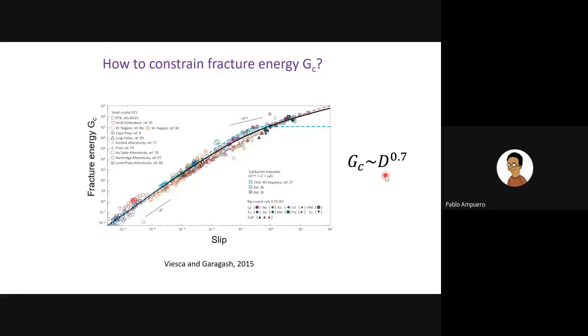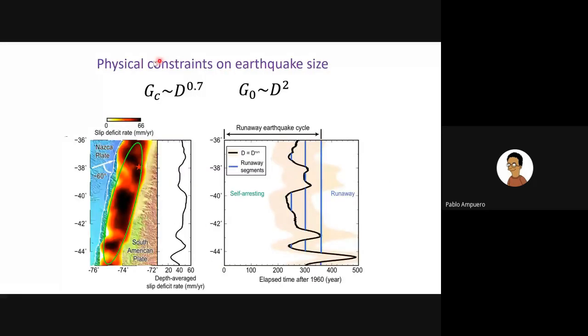So when we have these two portions of the earthquake potential, and if we take this slip as being the slip deficit that has been accumulated and that we can estimate from geodetic observations, so those are the coupling maps, one of which I showed earlier, we can use these potentials to make some statements about the potential size of an earthquake currently or in the future, because we know the rate of accumulation of this slip deficit.